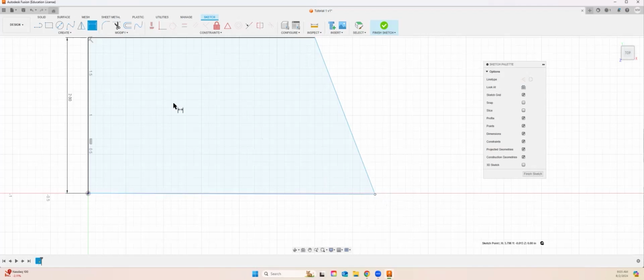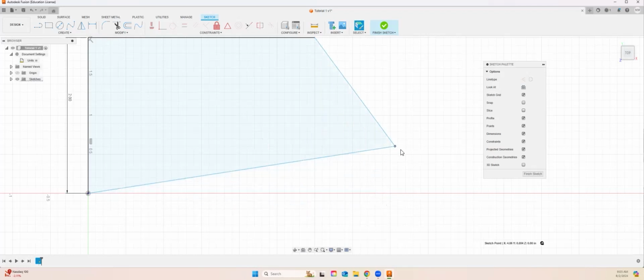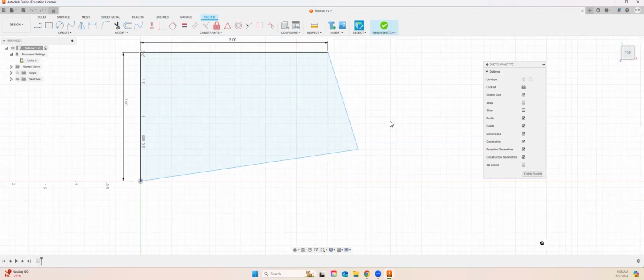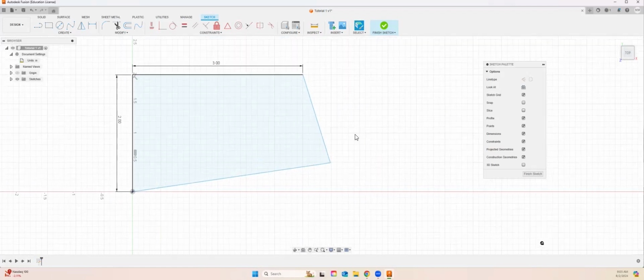And you can see that if I just click this out just for escape, anything that's blue, you can drag out. So you can see anything that's blue, that's why you can reshape it. You want a drawing that's fully constrained, fully dimensioned. That's when all the lines turn black. If you leave anything blue, sometimes this will happen.